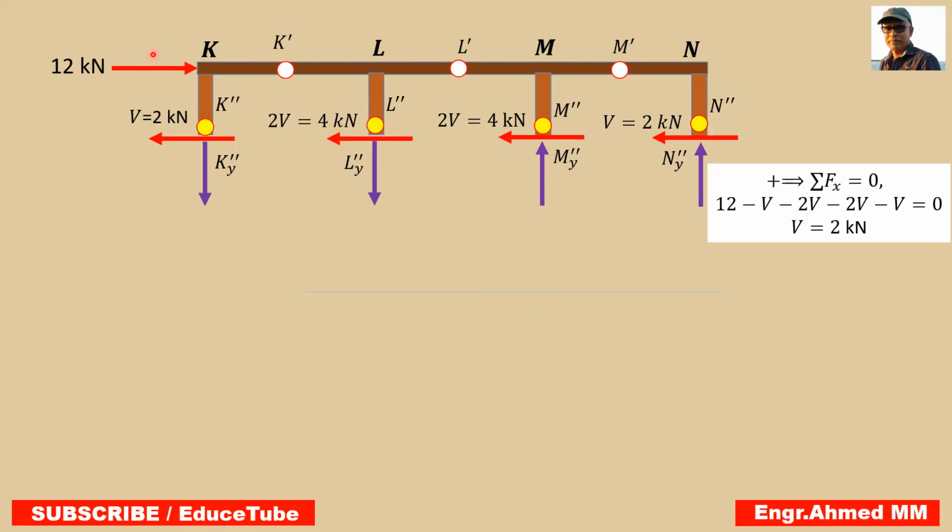As a general rule, we always start the analysis at the corner or at the joints where the horizontal load is applied. So surely we will start from here to determine the reactions at this point and at these points.